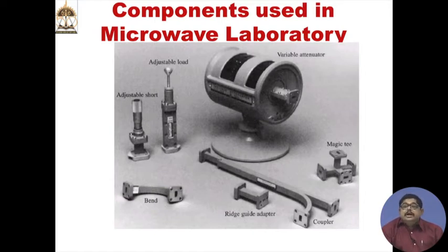One is a directional coupler, which is very important. Actually, this is the basis for separating, this device can separate the forward wave and reflected wave, and this is the basis of modern days replacement of this microwave bench, which is called network analyzer.